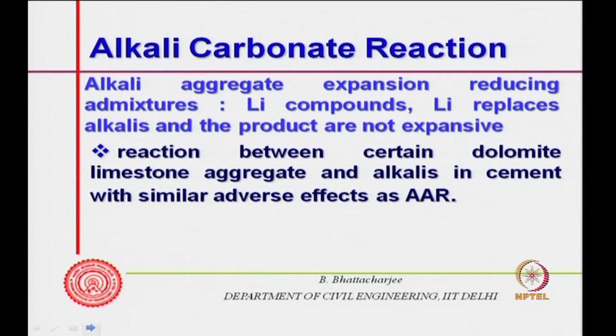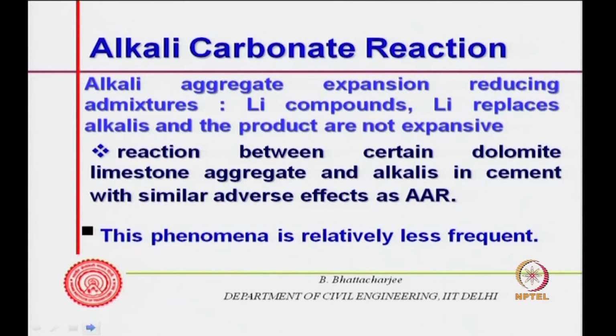Now, alkali carbonate reaction is important in some cases. Reaction between certain dolomite limestone aggregates and the alkalis of cement shows similar kinds of adverse effects, and this is called alkali carbonate reaction. So far we looked at alkali silica reaction or alkali silicate reactions, and this is alkali carbonate reaction. Of course, this phenomenon is relatively less frequent.